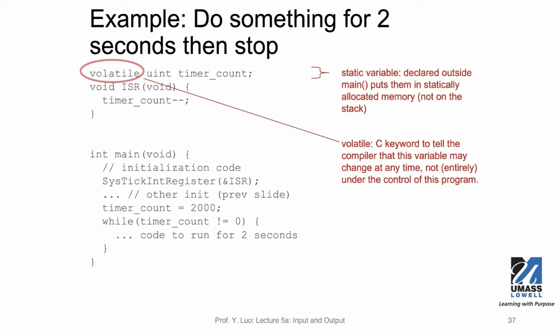If you have a value stored in the cache, then there's a risk that this ISR function or the main function will not see the real value, due to the conflict, the updates will not be reflected right away to be visible to either of these functions.